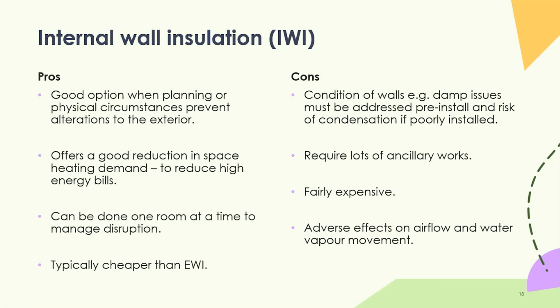and it's so typically cheaper than EWI. I would say that depends. Some of the situations you might find where you're having to maybe move sockets and radiators, and maybe some of the detailing of particularly ornate woodwork or ceilings or something like that, those can add to the cost of IWI.